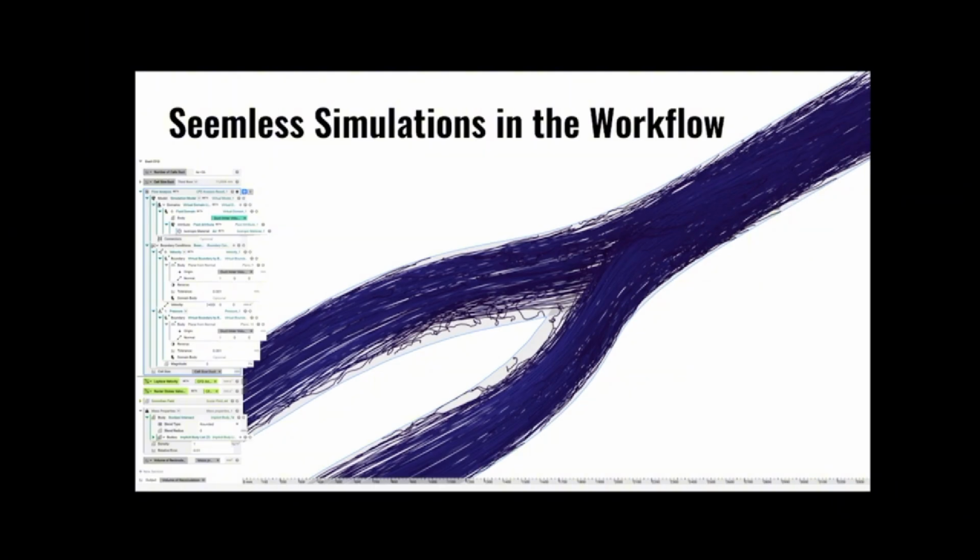So this duct is driven by some spline parameters, and to show you just how simple it is to set up a flow simulation in Ntop, we have this block structure here on the left. It's pretty much just linking Ntop existing objects to solver settings. In this case, we have the flow domain that we saw on the green slide earlier. We have inlet velocities and the pressure outlet just given as implicit bodies.